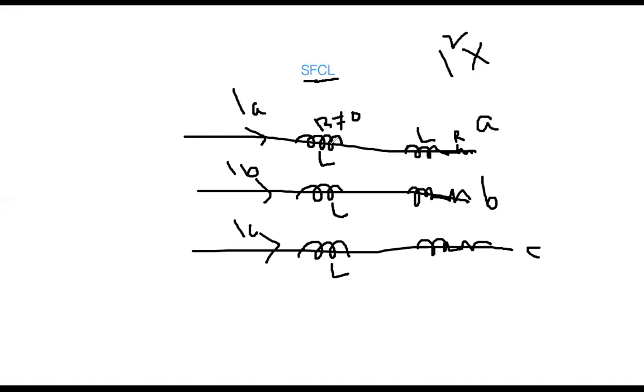You know the property of any conductor. Once current flows, gradually it will heat up and develop some resistance. Because current is continuously flowing, to maintain resistance 0, there is a refrigerator. So because the resistance is 0, it is called a superconducting fault current limiter. Now the thing is how it works.